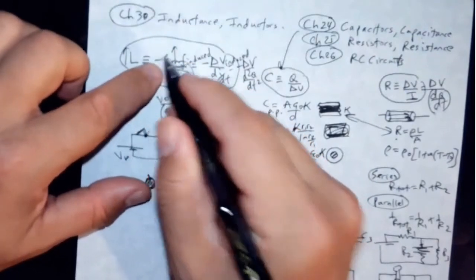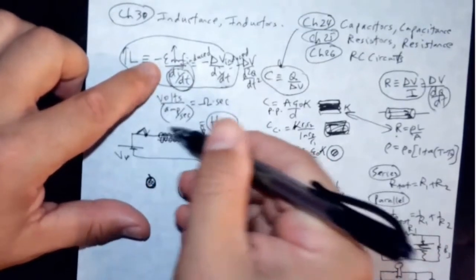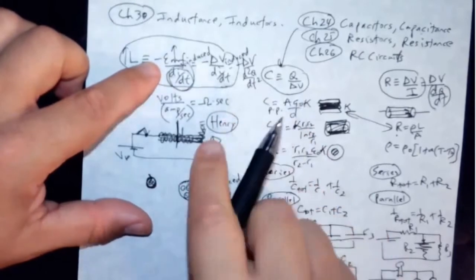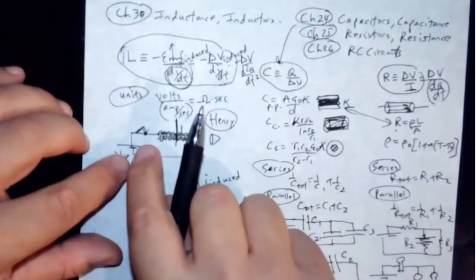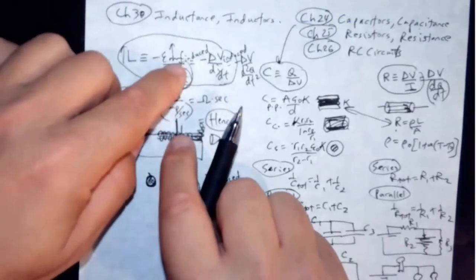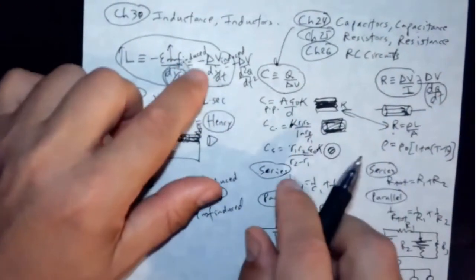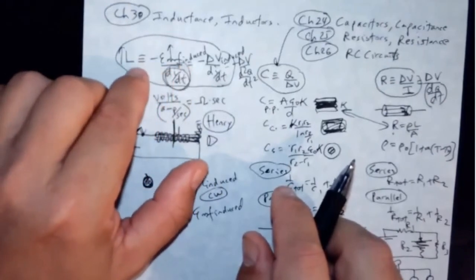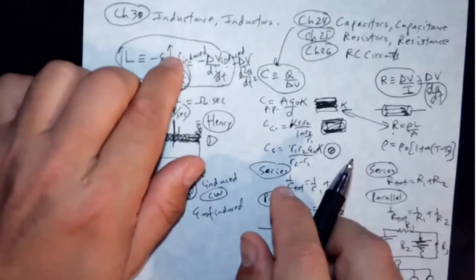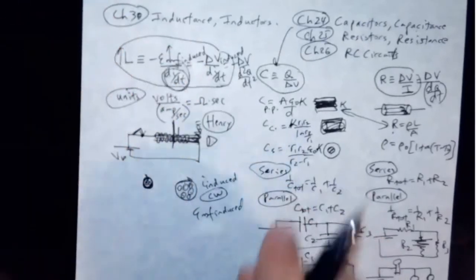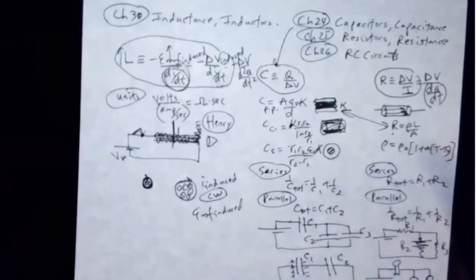And the reason why it's negative is because the EMF induced here is acting in the opposite direction. It's acting as if it's a battery opposing the original battery, you see? So this EMF induced is technically negative. So to make inductance positive, we say negative of negative, and that makes inductance positive. So that's why there is a negative there. Okay. Interesting concept, right? I think most people know more about resistance and maybe capacitance, but fewer people have heard of inductance. It's more of an advanced topic.